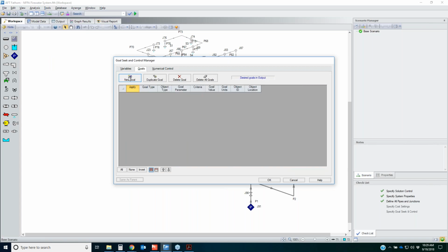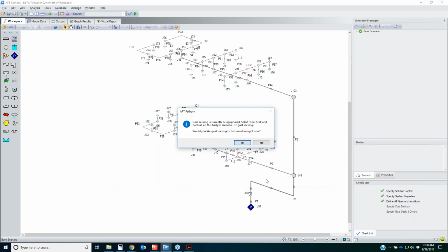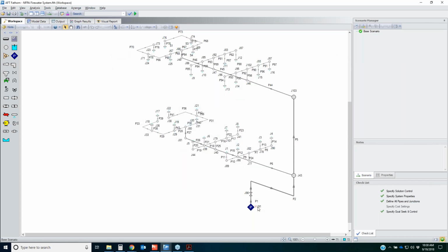Therefore, for the goals, when you create a group, there's a new goal type available, not just point goal or differential, but a group goal. So this is how I'm going to do it. I'm going to click on group, and do a group max min. This is where the group has to achieve either a maximum or a minimum value of a certain parameter. Here they have to meet a volumetric flow rate greater than or equal to 42 gallons per minute. Then you specify your group, which is going to be my spray nozzle group. Easy enough. You click OK and turn on the GSC calculations.